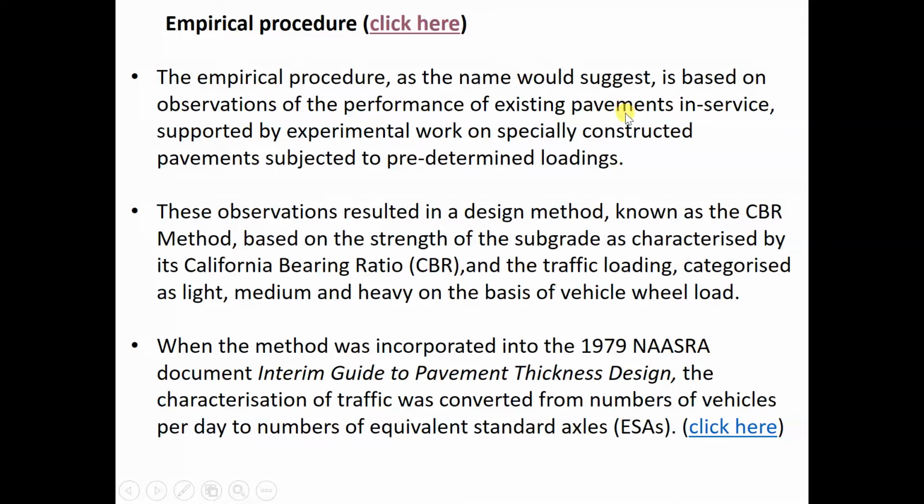They probably have certain roads. The roading authorities do some observations on that road to come up with the strength and see how well it performs against all the traffic, and therefore they have a certain thickness of the asphalt and how it performs.